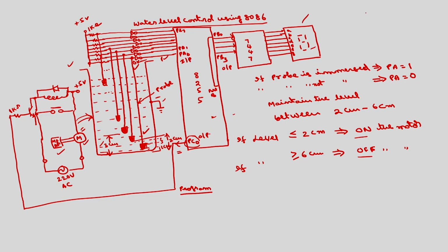So what is the control word register? This is port C lower, I want it as output port, 0. Port B, I want the output port, 0, mode selection for port B is 0. This is port C upper, I want to have the output port, and port A I have to operate as input port, and mode selection for port A will be mode 0. And this will be 1 for bit set, control mode, so it will be 90H.